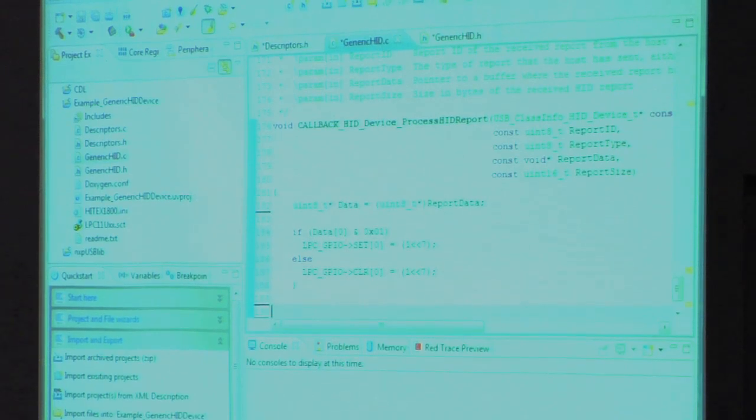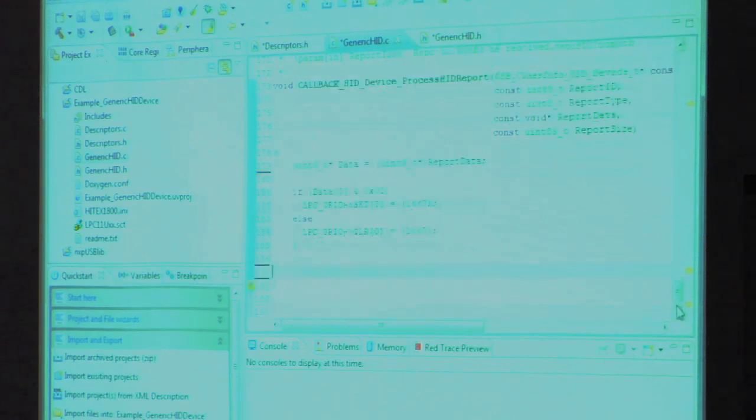So this register allows you to set particular bits. If I'm sending a 1, the LED is going to turn on. And if it's off, I'm going to clear that bit. So I have another function called clear 0. That's 0 in parentheses 0. That's port 0.7, that's what that one shift is. So everyone understand that part? Fairly straightforward.